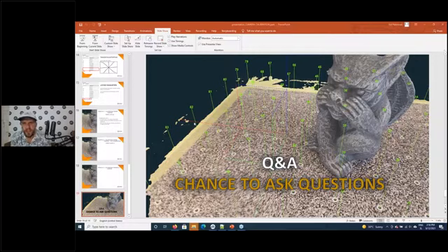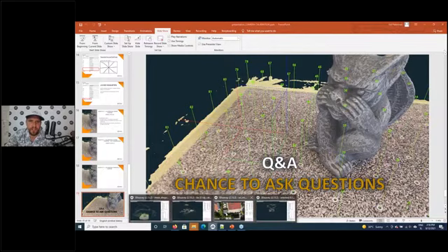For Mavic Air 2 Pro, this drone has been around for a while now. So for this one, the parameters are already in 3D Survey. You can do one small calibration project for yourself, place like that, place 9 ground control points on a small area, maybe 50 by 50 or 100 by 100 meters, and do the camera calibration and check the parameters.